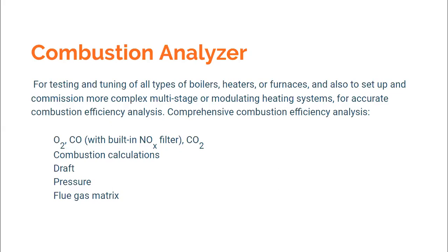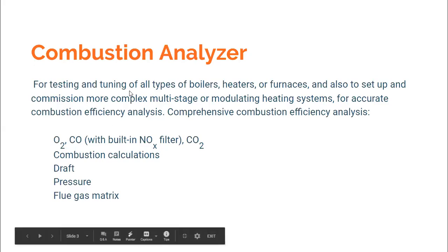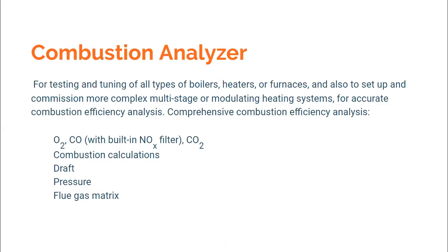So this is a very handy tool, and it is indispensable in fact, because without this you cannot comment on whether the combustion phenomenon which is happening is proper or not. And because we cannot measure that, we won't be able to tune the boiler. Tuning means what? Tuning means you need to control the air to fuel ratio in the boilers or in the furnaces so as to optimize that. Okay, so this is a very handy tool.